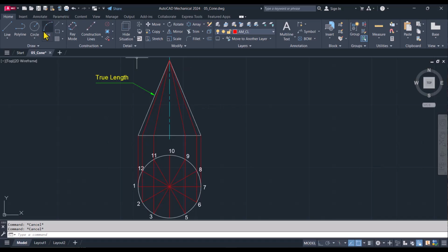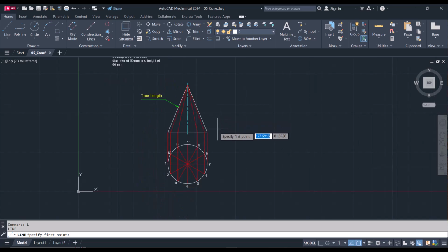Now I'll draw some line, some line of length 65. Let me switch the layer back to layer 0, then start the line tool again. So I can draw some line of length 65. Okay, and then I'll need the included angle here. I'll need the included angle there. You see what I mean in a minute.